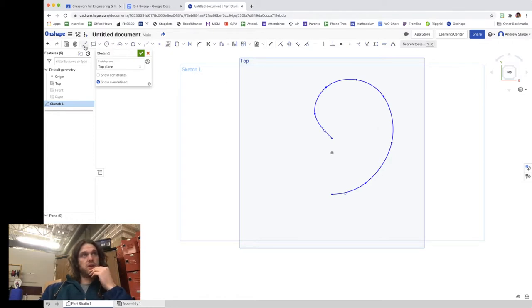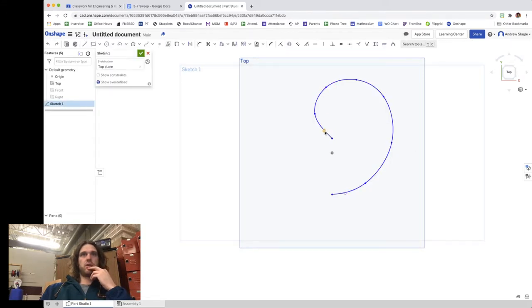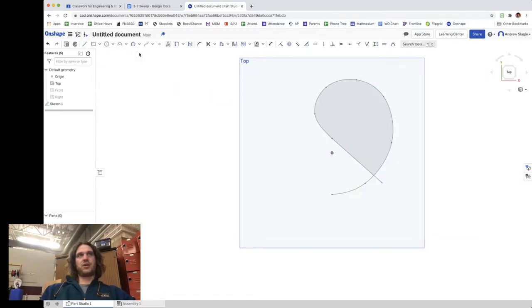What we're going to do is I'm going to finish my sketch. Now, we run into an issue. You may have asked, hey, why didn't you extend it all the way to the other side of the pretzel? So why not connect this line here? The problem is the sweep ends up intersecting with itself, and when it intersects with itself, it doesn't actually generate. So I'll show you that, and I'll show you how to correct that problem.